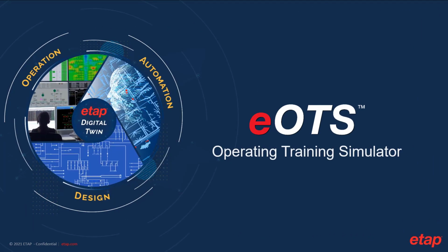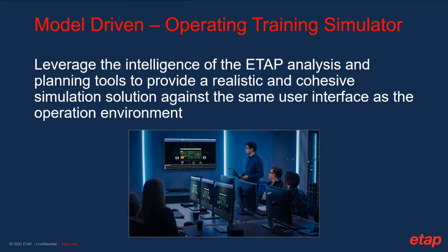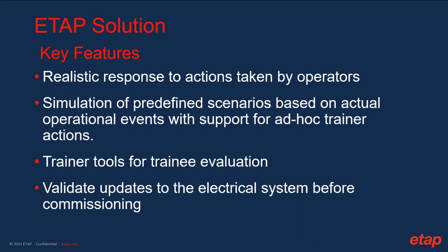Next, I'd like to discuss the eOTS product, which is the Operator Training Simulator. This is a model-driven operator training simulator, which means that we leverage the intelligence of the ETAP analysis and planning tools to provide a realistic and cohesive simulation solution against the same user interface as the operation environment. Some of the key features include a realistic response to actions taken by the operators. This is because it is a model-based solution, so you actually get that system response, not just seeing if the circuit breaker is opened or closed.